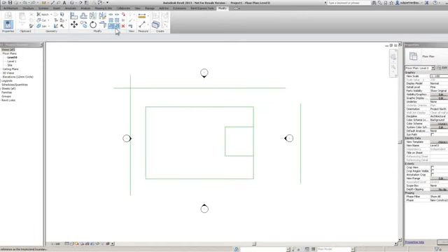This time I'm going to do the Trim/Extend Multiple Elements, and again I'm going to pick this one. I haven't pressed enter or anything, it's literally just the first line or object that I pick. In multiple elements, it will stay the trimming edge and extending boundary all the time until I come out of the command. So anything that I select will either trim or extend to it, depending on the situation, or like I've just done there, clicking on nothing, it will drop that.